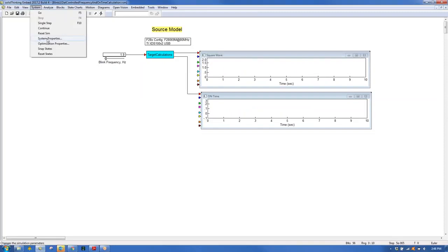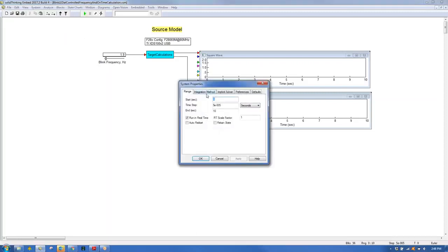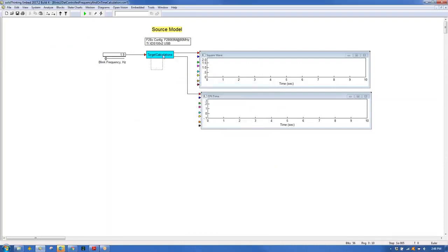Well, they're going to be identical up to a certain point, because the JTAG interface will only transmit data at about 200 hertz. So you will lose some data in that interface, and I'm going to talk about how to overcome that shortly, but just plotting it out like I have it, you will lose some data.